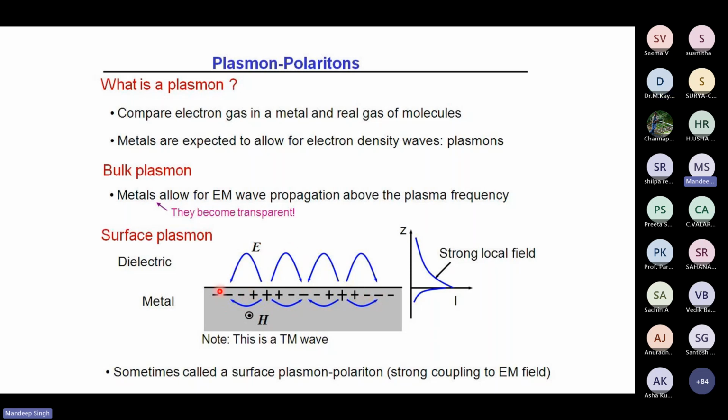Okay. And you can note that if you use this geometry, that is metal-dielectric, it will support only TM waves. And next, the very important question is the field strength. That is how we can observe the field strength. You can see there is a graph of intensity with respect to position on the axis. You can see that the strength decays exponentially. And the strength in the dielectric is more compared to the metal, because there are ohmic losses in the metals. Due to this, the strength is very less on the metal side, but more on the dielectric side at high frequency, right?